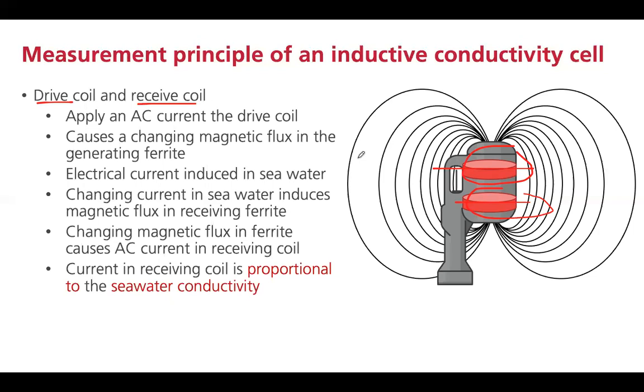It turns out the current that's driven within the receiving coil is proportional to the seawater conductivity. Actually, the conductance, but you can transform that to conductivity with the cell constant. That's the basic principle of how an inductive cell works.